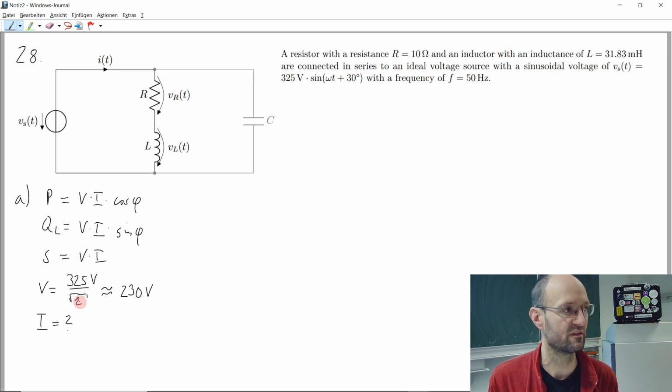It's kind of a fixed factor, and it depends on the waveform that you have. For a sinusoidal waveform, it's the square root of 2. If you have a triangular waveform, it's something different. If you have, I don't know, a rectangular waveform, it's something different. I would leave it at this, because otherwise I think we lose too much time in answering this question.